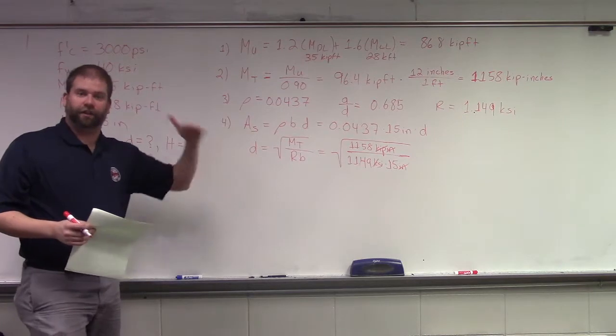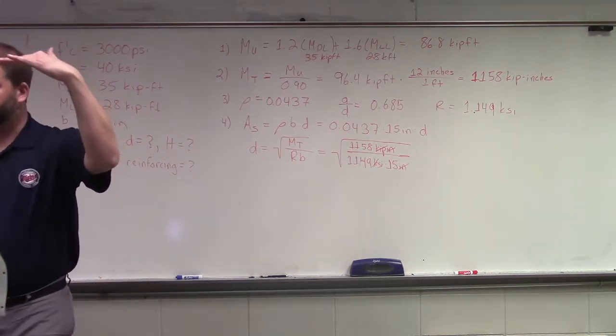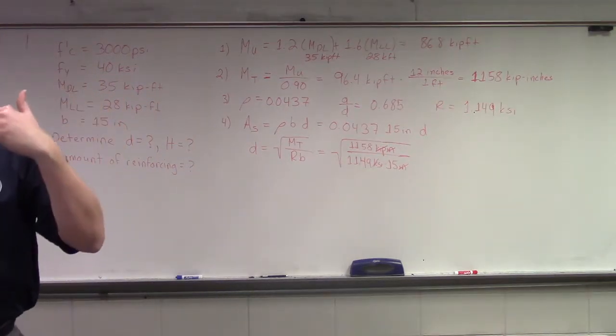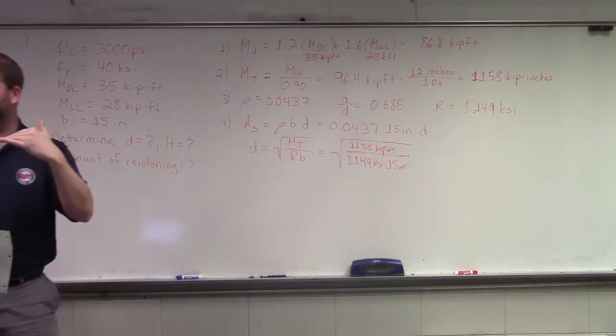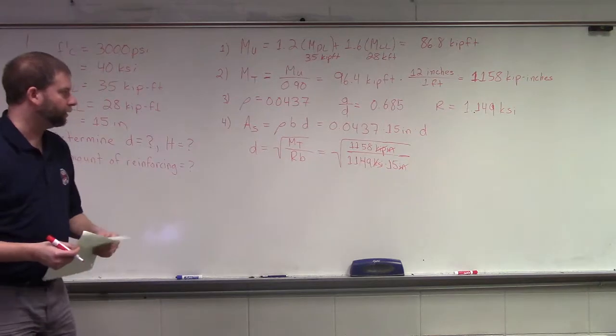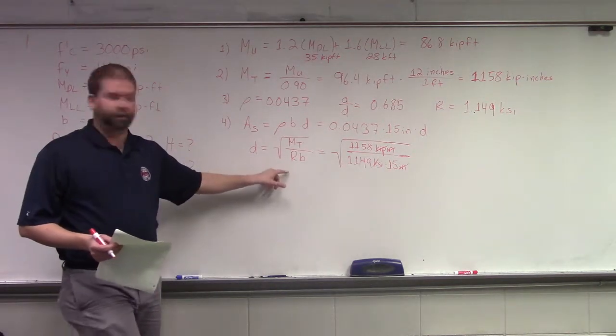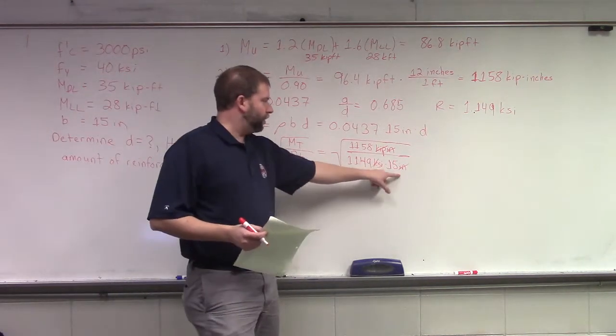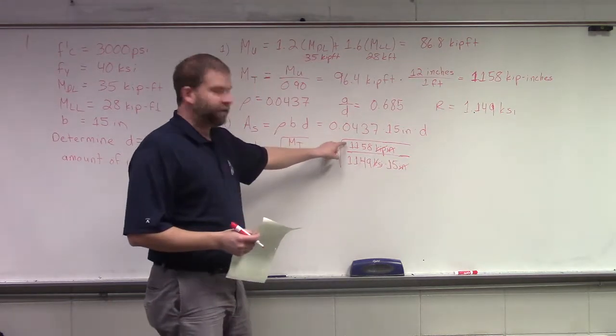What are we determining? Dimension D, right? The distance from the top face of the beam to the middle of the steel. We're going to measure that in inches, so our dimensions are good. As long as you're aware of what units you have, we're ready to go.